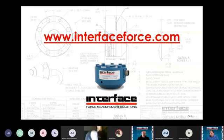Another question here: what is the maximum sampling frequency for strain gauge load cells? Again, I think Keith touched on that. It's going to depend somewhat on the model, but hundreds of hertz is certainly adequate. If you start getting close to the natural frequency that's posted on our data sheets, we'd definitely review the application with one of our application engineers.